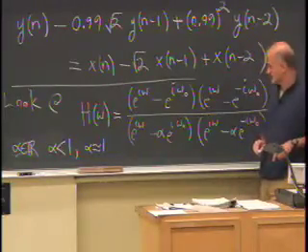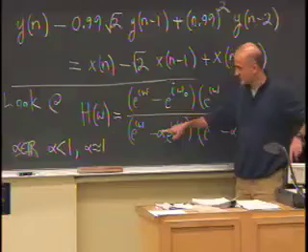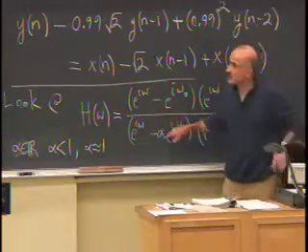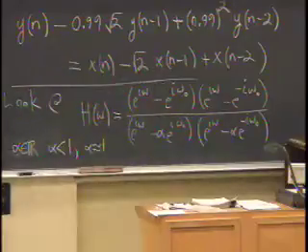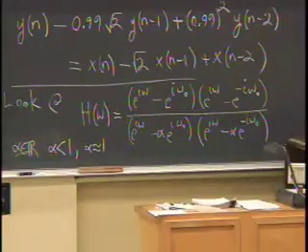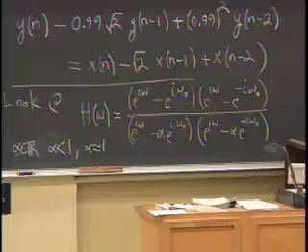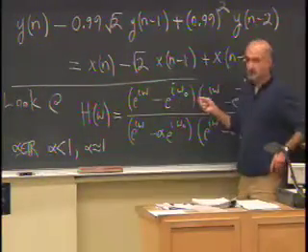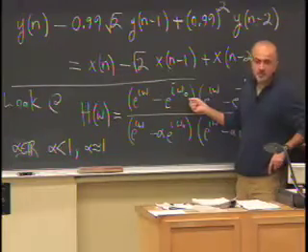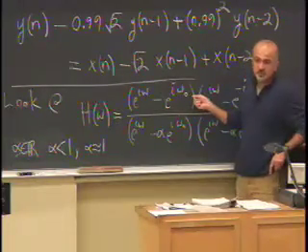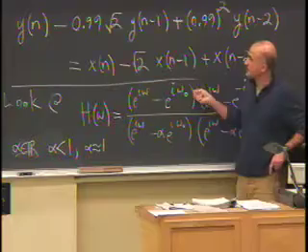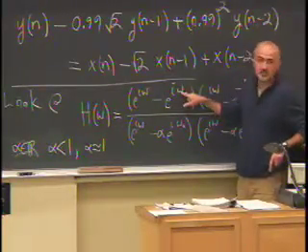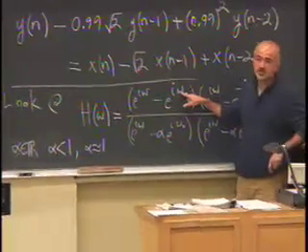Okay? I want this to be in its polar form. So alpha has to be positive. And for this to be a notch filter, alpha needs to be pretty close to 1. So in this case, it was 0.99. So you can, at your convenience, write out the difference equation corresponding to this filter. It's just a generalization of the filter in the top, except this is for an arbitrary notch frequency, omega naught.